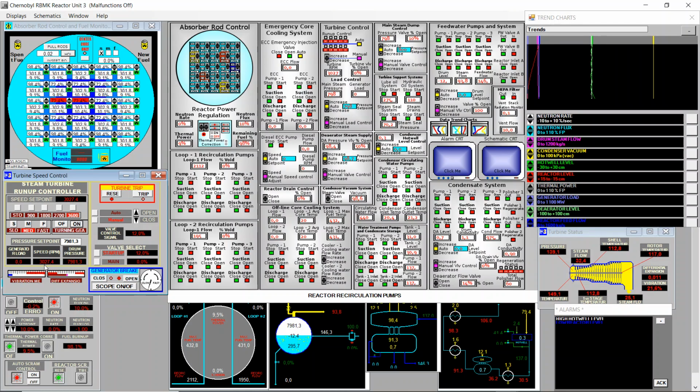Okay, we're at 3000 RPMs. I will start to decrease the opening of the valve a bit to 11. I know I need 5% at the end, so I will decrease. When I approach the nominal value of velocity, I will decrease it to the value I need. We're at 3000, almost 400. We're at 200 RPMs from the nominal value.